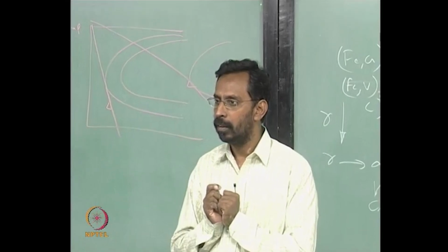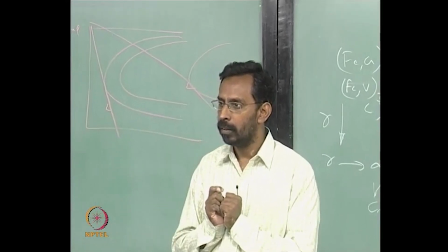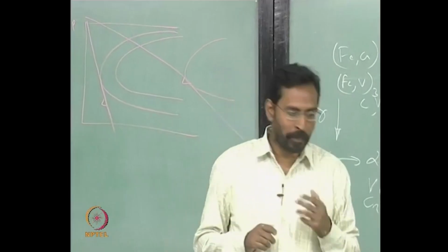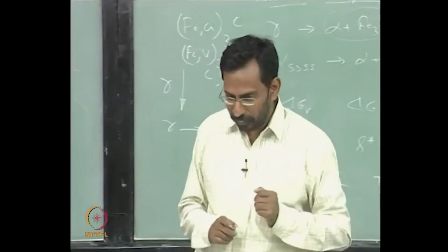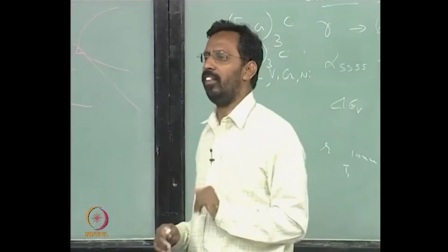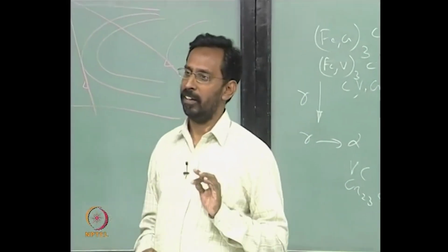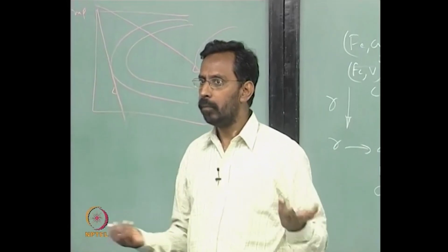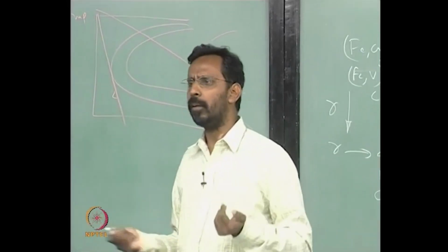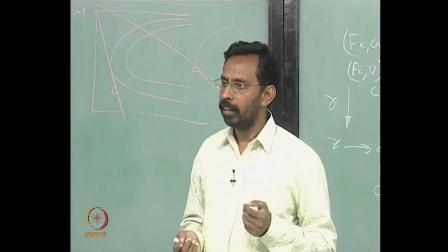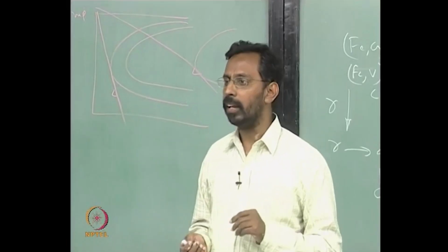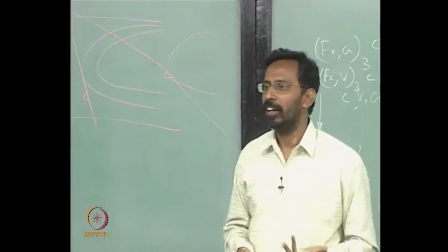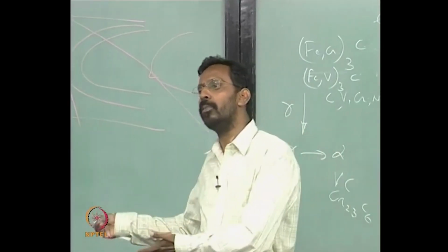Still, how is it possible, sir, for a single atom to replace such a bigger or smaller atom? It is not replacing. You have to understand that there are always vacancies inside a structure. But still, how will such a big atom go and sit in a smaller place? If it cannot sit, it will precipitate with something else. The dissolution takes place as long as it can dissolve. If it cannot dissolve, it will precipitate.